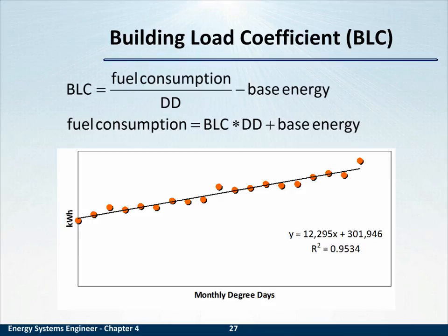With the building load coefficient being defined as fuel consumption divided by degree days minus base energy load, you can plot your fuel consumption by degree days. Degree days is a calculation that you can do based on weather data.